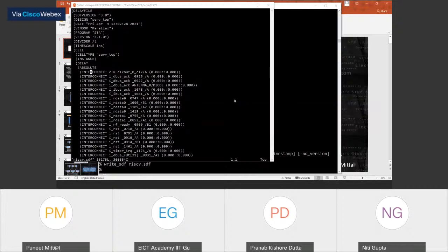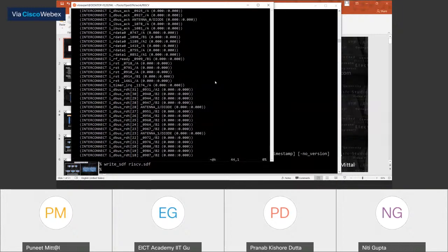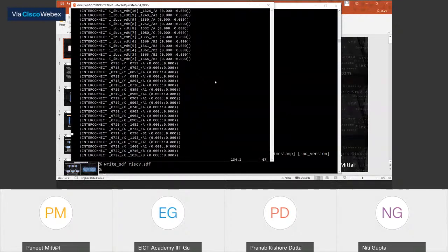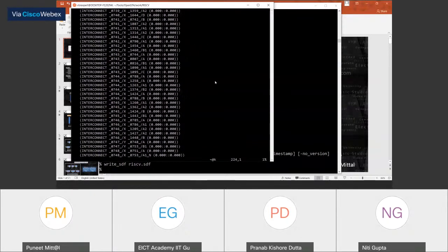The RC related information comes after the parasitic extraction. Since there is no such file, the net delay is supposed to be 0 only. Since there was no wire load model, all the net delay is supposed to be 0 only. So that's the reason, if you see here, everything is 0 for interconnects. And see the complete design, complete interconnects, everything is here.